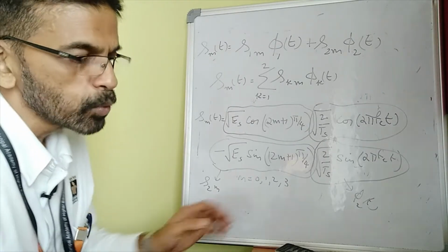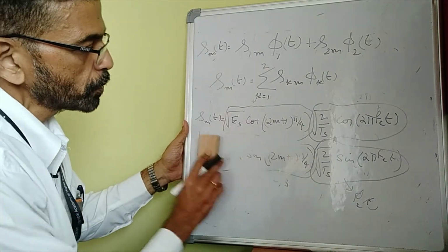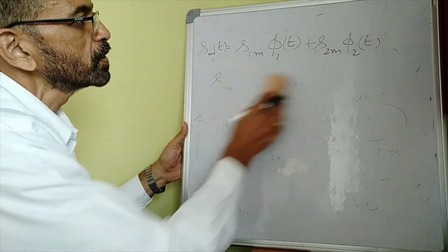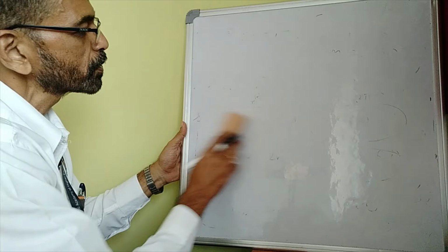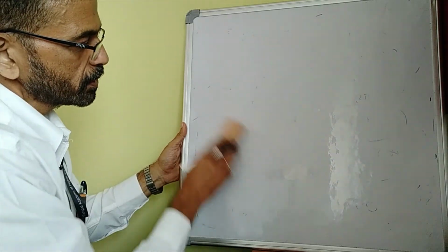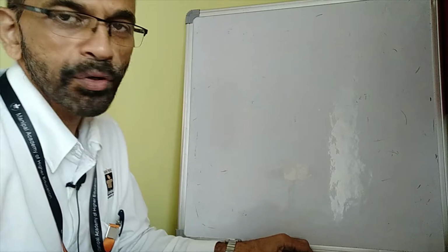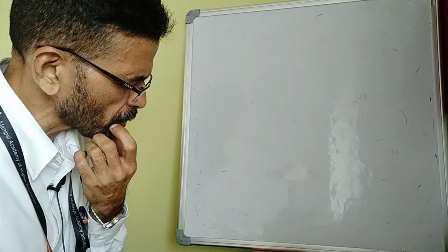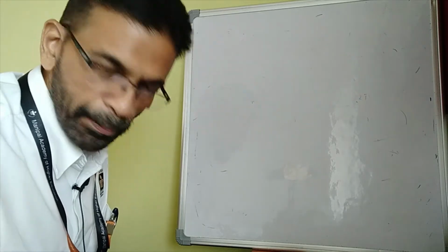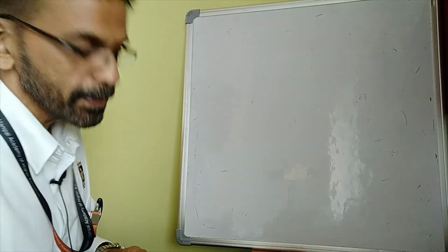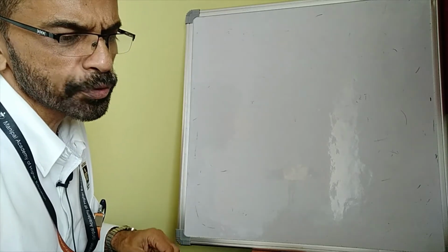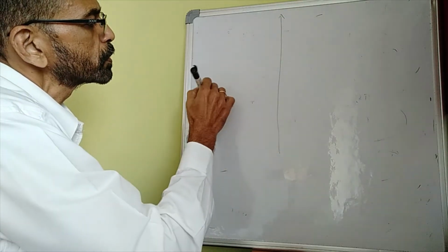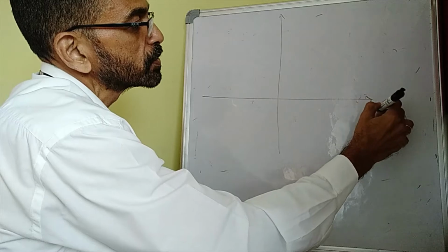We will now draw the signal constellation for QPSK, just as, if you recall, we drew the signal constellation for M-ary FSK with M equal to 3, wherein we got a three-dimensional signal space. In general, for M-ary FSK, the signal space will be M-dimensional. Here in QPSK, as we saw just now, the signal space is two-dimensional, and we can draw the signal space like this.